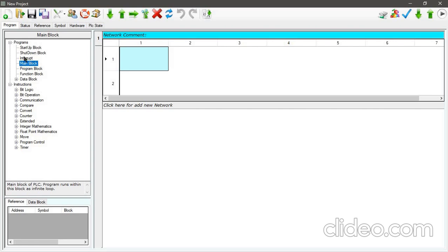Okay, interrupt, it's an interrupt block. Maybe during the program cycle, you can call an interrupt block to work, and it stops the program cycle and goes into that interrupt block, scans the necessary program and does the functions.